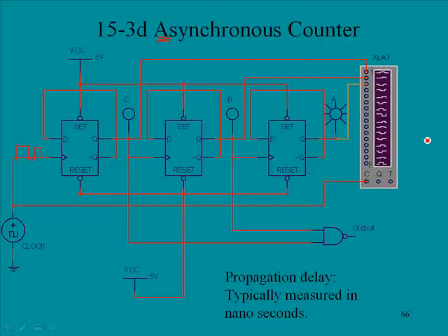They work well. There's really not a problem with these, except that at higher frequencies they can become problematic, because of something called propagation delay. Your text mentioned it earlier. I didn't mention it then, but I will mention it now. Propagation delay is the time that it takes a signal to move from the input to the output.